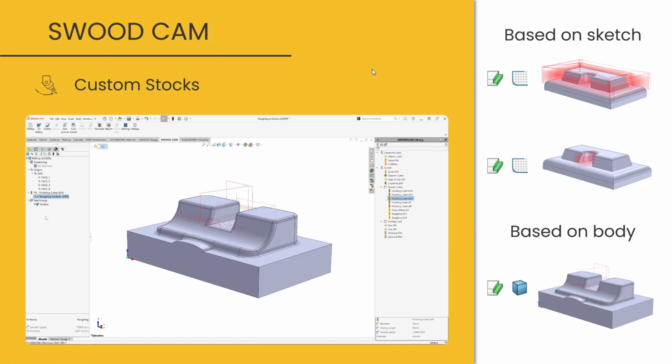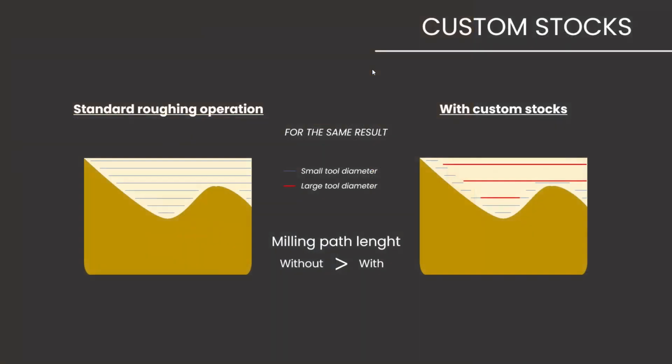After rebuilding, the algorithm identifies the milling path between the body to be removed and the 3D model. We can see that we can use this custom stock to create more efficient milling strategies. This is what we can see in the example on the left hand, where we have the trajectories of a small tool shown. And now, on the right hand, the trajectory is made thanks to the custom stock features with the first roughing done with a large cutter. Then in blue, a localized roughing trajectory is created with the small tool. So we can combine tools in these trajectories to create quicker roughing milling.